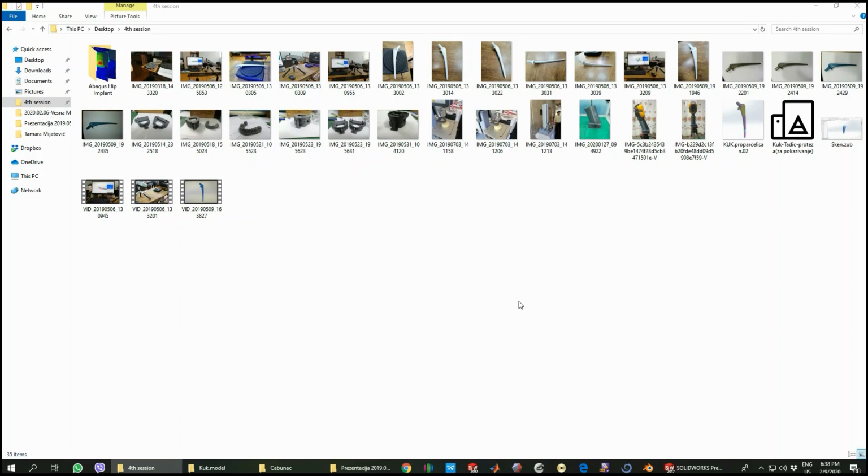3D printing shows its advantages in manufacturing of complex parts when it is hard to attain your model with conventional technologies. But for 3D printing you need to have your model in digital form. You need to have an STL file to work in your slicer software. So first you have to attain your model, either by CAD modeling or some sort of 3D scanning.